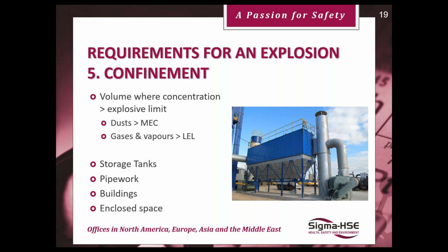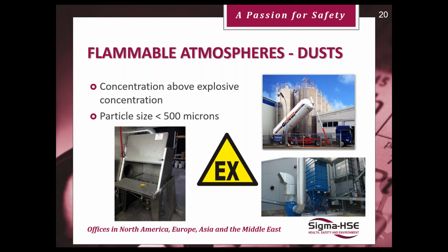But as I said right at the opening, if we want to have a flammable atmosphere containing dust, we need that concentration above the explosive concentration, and we need the particle size to be less than 500 micron, because if particle sizes are larger than 500 micron, it's a lot more difficult to get those powder particles dispersed in air and producing that dust cloud.